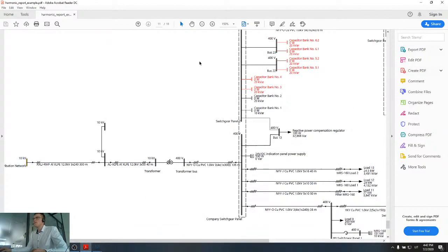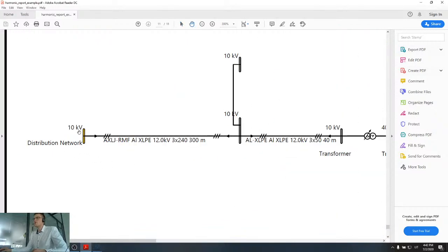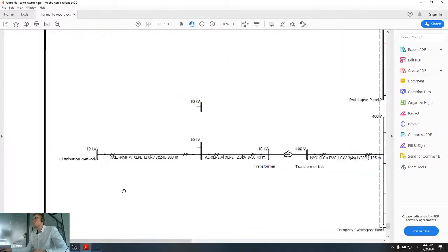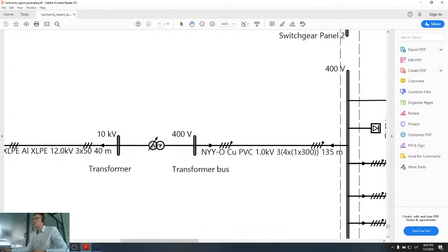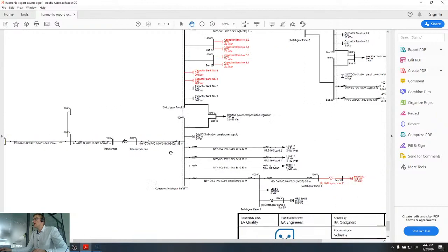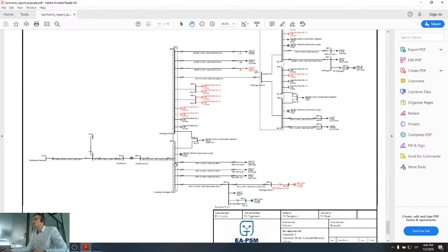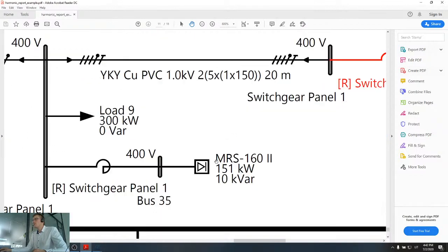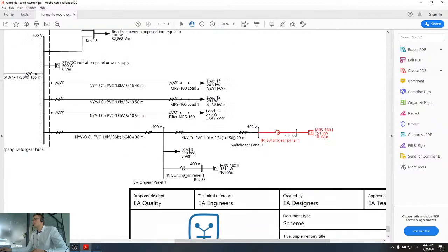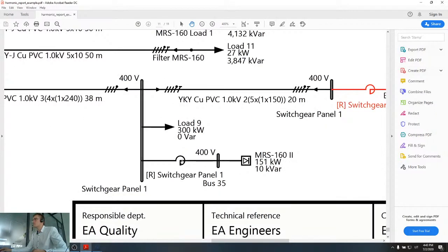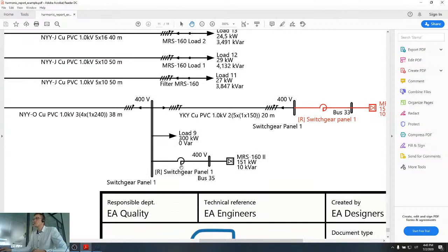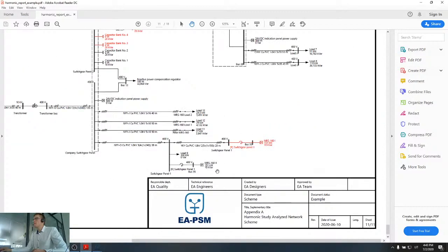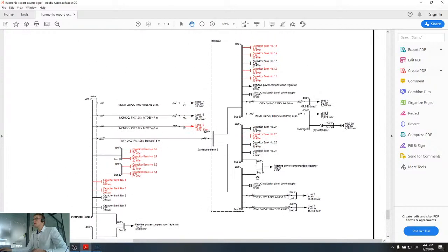We have this medium voltage network where our client's network is connected. We have a transformer reducing voltage from 10 kilovolts to 400 volts, and the electrical network of the client constructed of nonlinear loads, variable frequency drives connected to 3 reactors in order to reduce voltage unsymmetry, and another type of equipment.